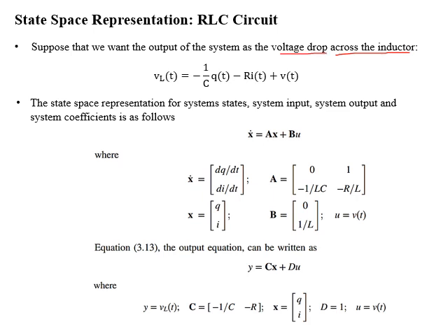State space model of linear time invariant system can also be represented in matrix form, which is x dot equals Ax plus Bu, where A is system matrix and B is input matrix. These matrices contain coefficients of state variables and input from first order set of differential equations.